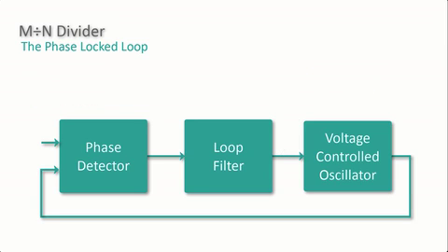Yeah, but we're not putting an FM signal into the phase-locked loop. We're putting in a pure, constant frequency. So what will we get at the VCO output? Well, we'll get a pure, constant frequency. So what's the point? Well, the point is in the feedback loop.